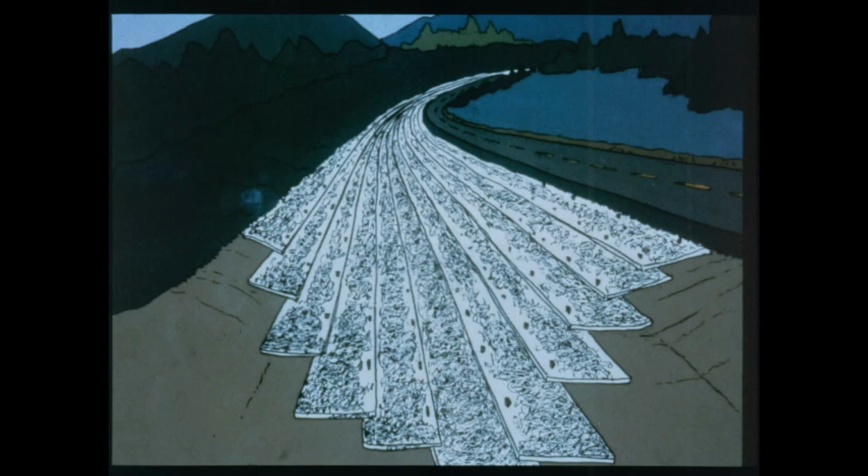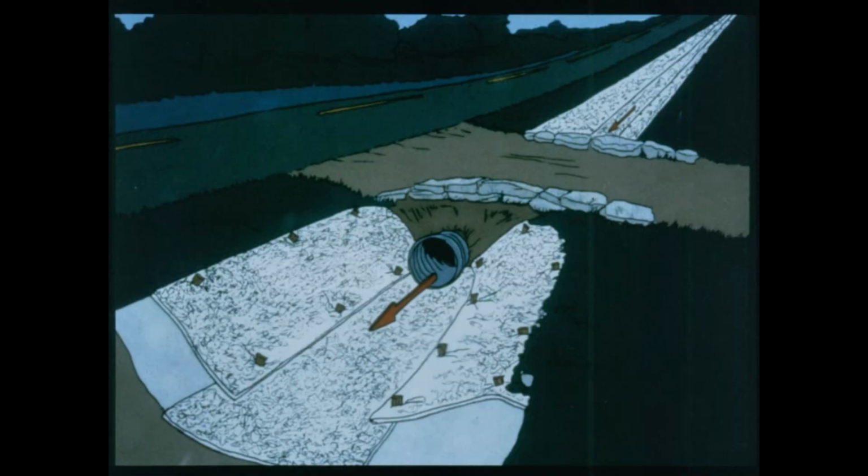Most channel installations require a large number of anchors to assure that the matting will stay intact and in place. But providing this proper anchorage can be time-consuming. Thus, careful inspection of the finished installation is essential, especially in deeper channels and other high-energy applications, such as culvert outlets.